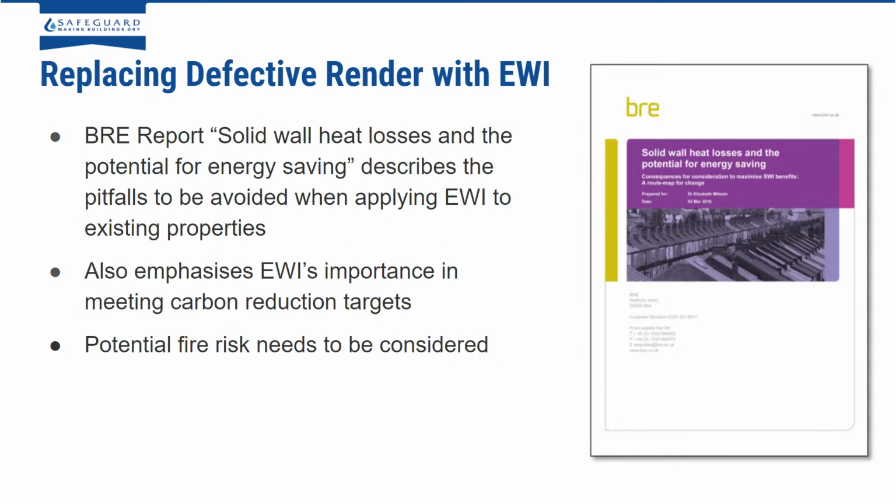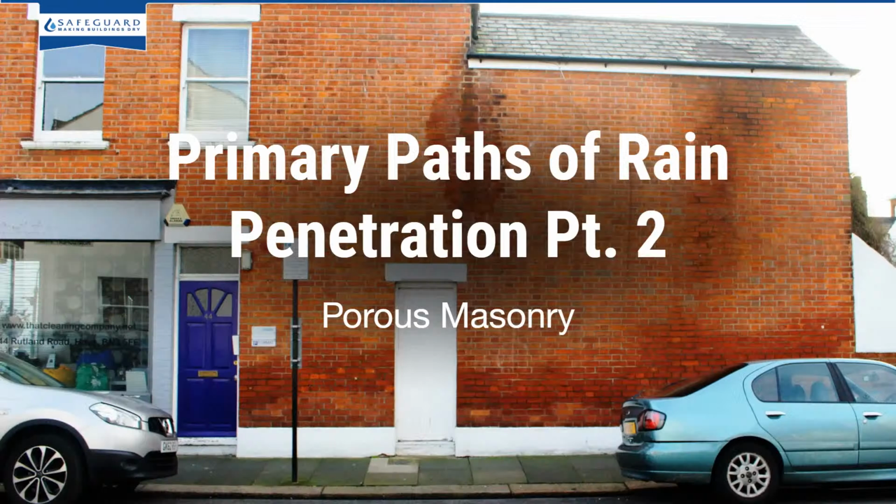So you can see here that a BRE report talked about solid wall heat loss and the potential energy savings, but also described the pitfalls to be avoided when installing EWI. It emphasises the importance of EWI in terms of meeting carbon reduction targets, but also the damp issues that can become apparent if it's not correctly installed. So that's the masonry defects.